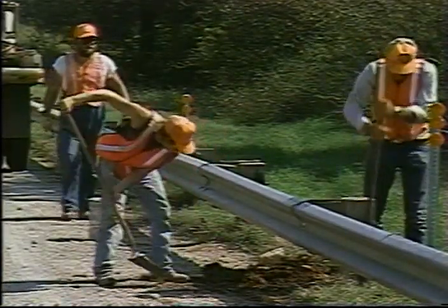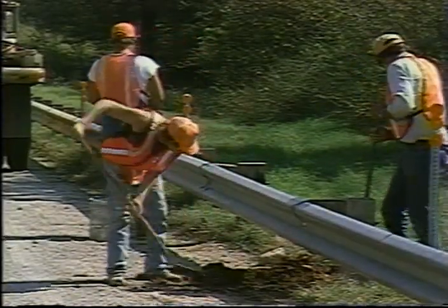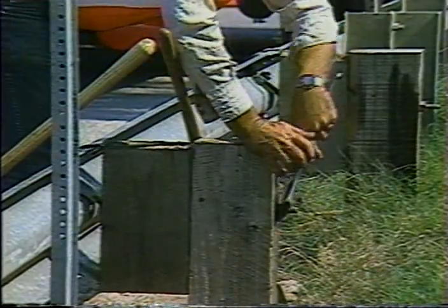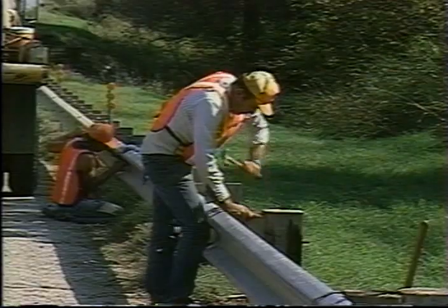Backfill and tamp the soil around the base of the post until they're firmly embedded in the ground. If the posts are near a slope, there must be a minimum of 2 feet between the post hole and the top of the slope. When all the W-beam has been hung, all the nuts and bolts should be firmly tightened. And where needed, toenail the wood post.